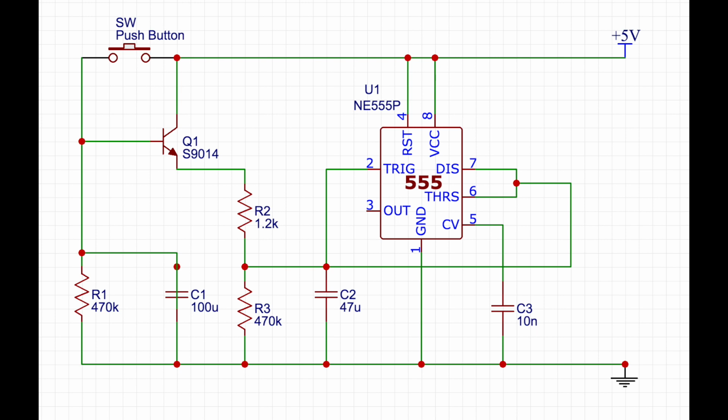In a previous video about servo testers, I showed you how to calculate the values of the components for a 555 timer circuit. So I'm gonna link the video in the description down below. For a while, let's just put together this circuit. You guys can change the values and see how it changes the behavior of our game. It's important to remember the output pin of the 555 timer should be connected to pin 14 of the CD4017B.